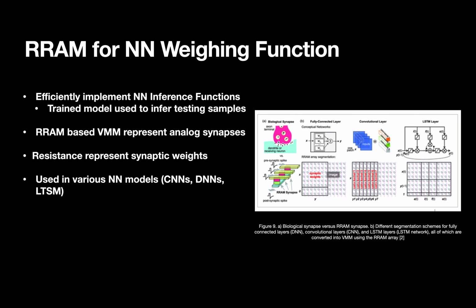For these models, the input vector and the feedback of the output vector are encoded in voltage format and then fed into the RRAM arrays in parallel. The intermediate computation results come from different columns of the RRAM array simultaneously, and therefore this sort of parallel execution can dramatically improve the throughput.